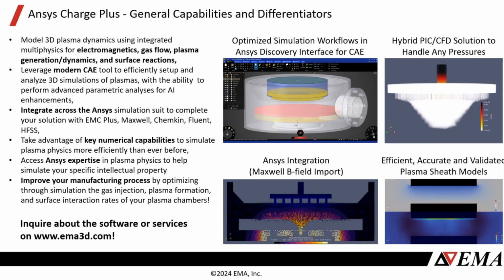And in the future, in the roadmap for 2025, we are working on being able to solve for reactions directly inside the tool. So these would be reactions associated to the bulk plasma. If you want to model much smaller behaviors and features, then you can extract the information that you get from this simulation about the ion densities, velocities, and momentums at the surface and pass them to another tool, for example, a Synopsys tool that can actually model the etching process. And as an initial condition, instead of having a fixed momentum and density, you would have the information from the simulation that we solve here.